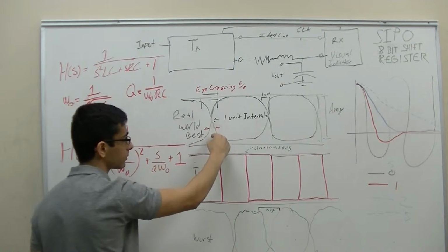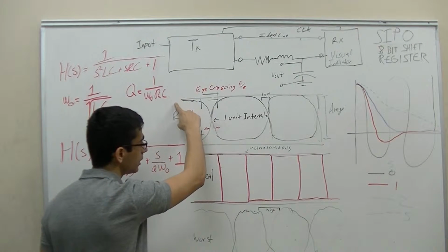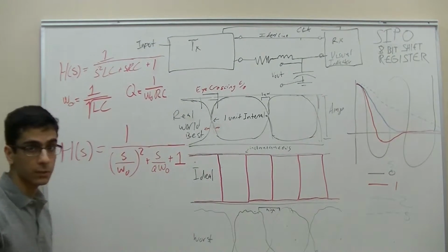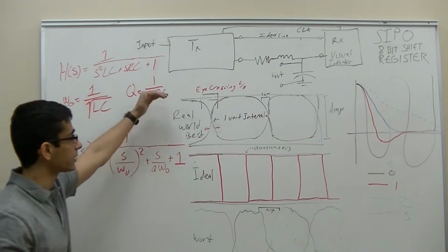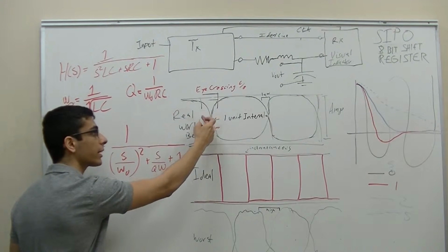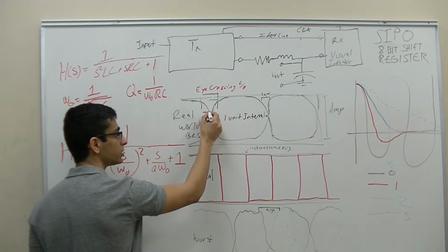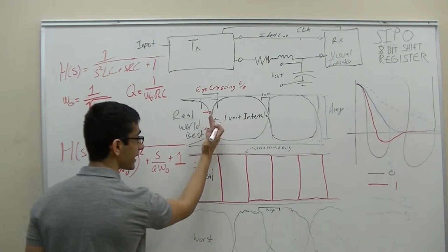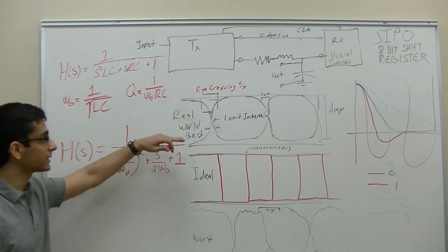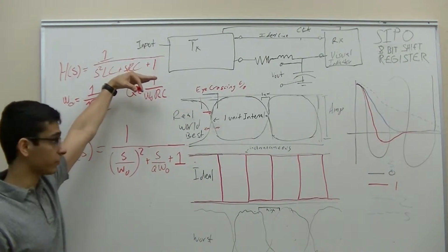If it goes from the top to the bottom, it'll shift from a 1 to a 0, and depending on the clock it will read either a 1 or a 0 depending on where it is read in reference to a voltage. So there could be a reference voltage here, and if it reads exactly at that time, it will read as a 1 as long as it's above that reference voltage.